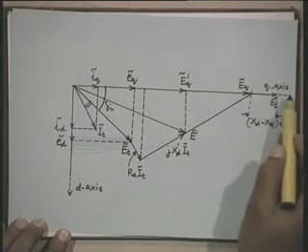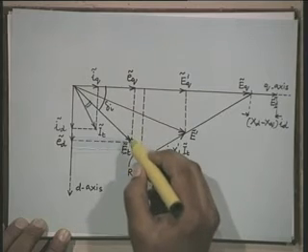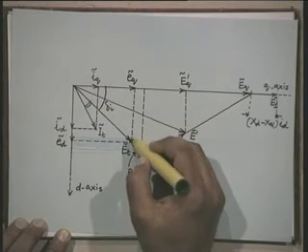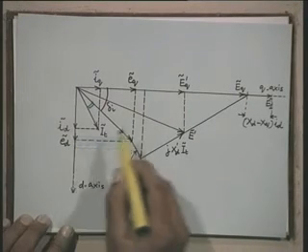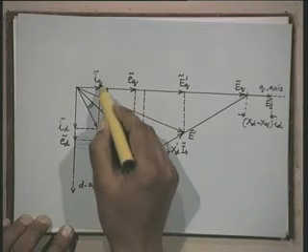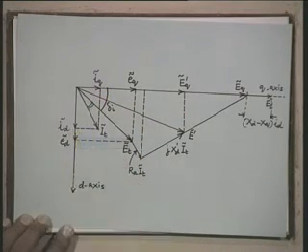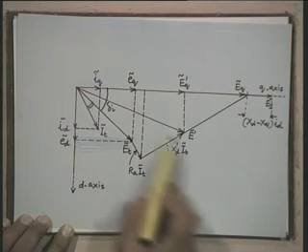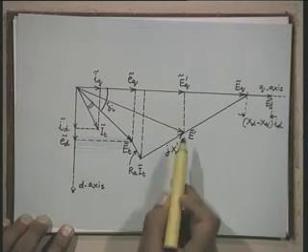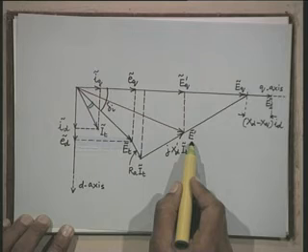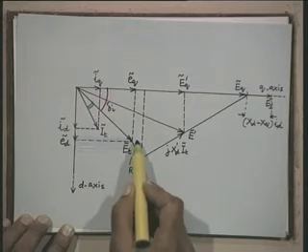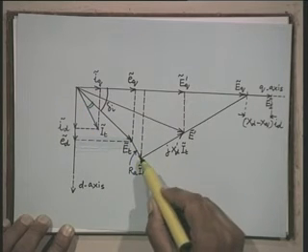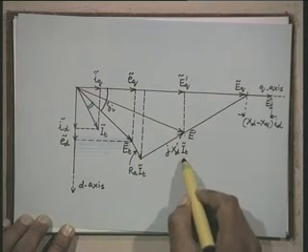Once this Q axis is defined, you resolve the terminal voltage into two components, EQ and ED. Similarly, the terminal current can be resolved into two components, IQ and ID. Then in this phasor diagram, we can show this term E prime, a voltage behind direct axis subtransient reactance. What you do is that you take ET, to this you add RA IT plus j times XD prime IT.